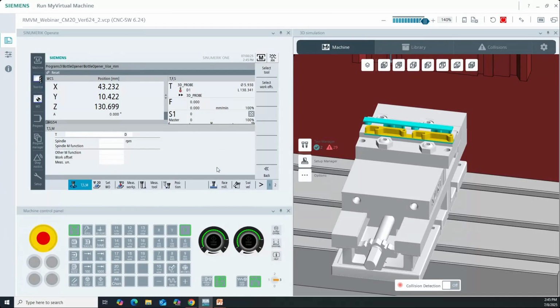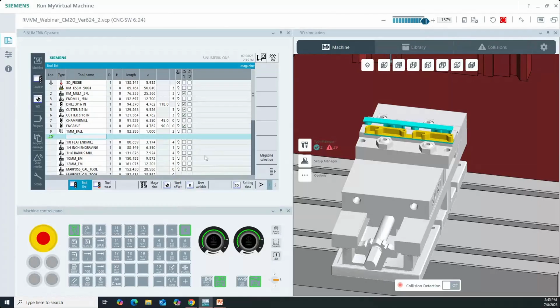So if the machine was commissioned with what we call our ISO mode, see how I have this H column? Mine absolutely is. What that means is I can actually run effectively straight FANUC programs in this machine. So if I just want to use it to do some basic proof out of a FANUC program, it's not going to be a true one-to-one digital twin to your FANUC equipped machine, but you can certainly run your FANUC programs through it and at least validate that the programs are going to work within this environment space before you walk them over to your FANUC machine. So you can get there. It's a little more of a hybrid.